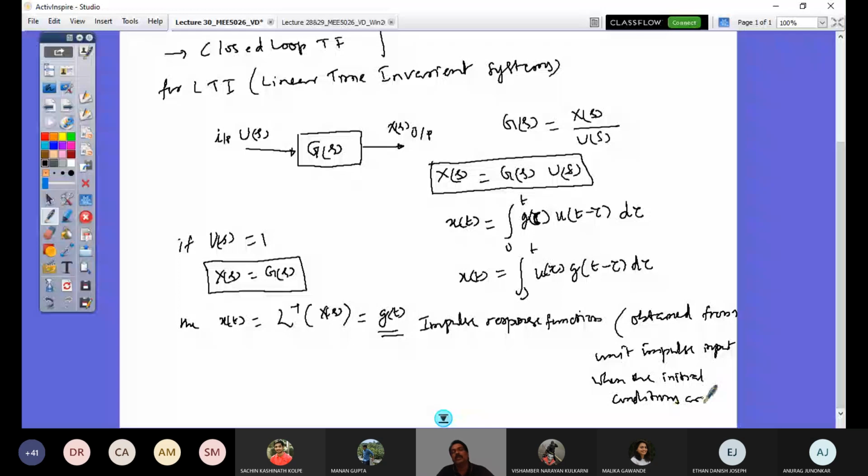That is what we will do in our laboratory test called a hammer test. So we have a hammer which has a sensor mounted at the tip of the hammer, a force transducer there. So when you excite the mechanical system with that and you have a sensor mounted adjacent to that, you would get your drive point response, and that response is what is called the impulse response.